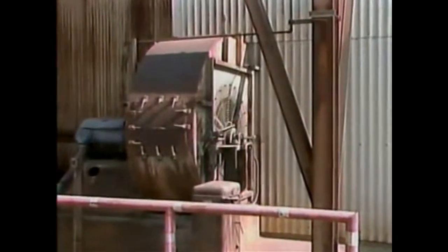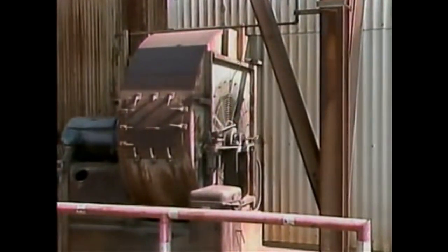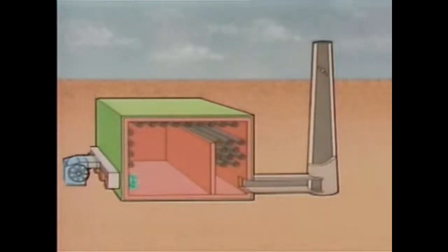Air and combustion gases are moved through forced draft furnaces by fans. This is a simplified illustration of a forced draft furnace. A fan, called a forced draft fan, draws air from the atmosphere and forces it into the furnace. On this furnace, the burners are mounted along one wall. The combustion gases flow through the furnace and then out through the stack.